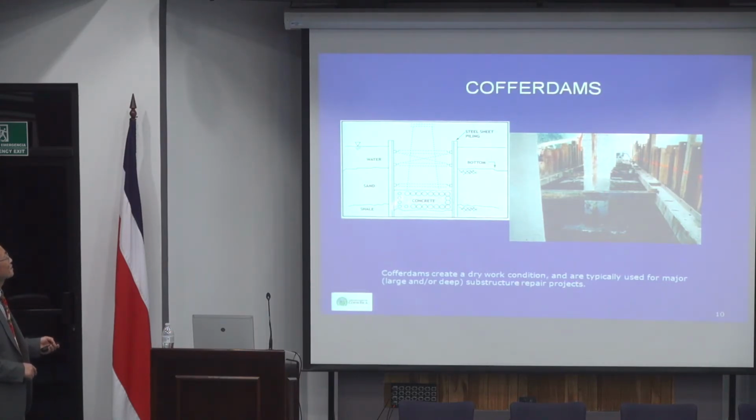But if you have a pier where the whole pier has undermining, you want to cast concrete, so you may just provide a sheathing. Usually you just press the sheathing in so that you can excavate into a dry condition, and cast concrete under the existing footing.